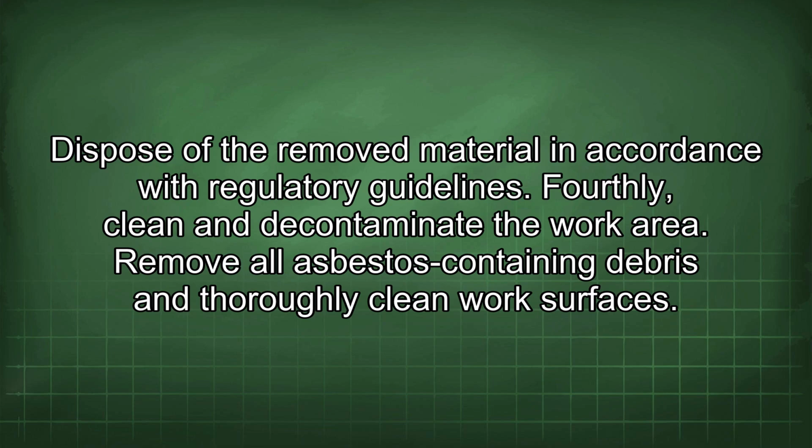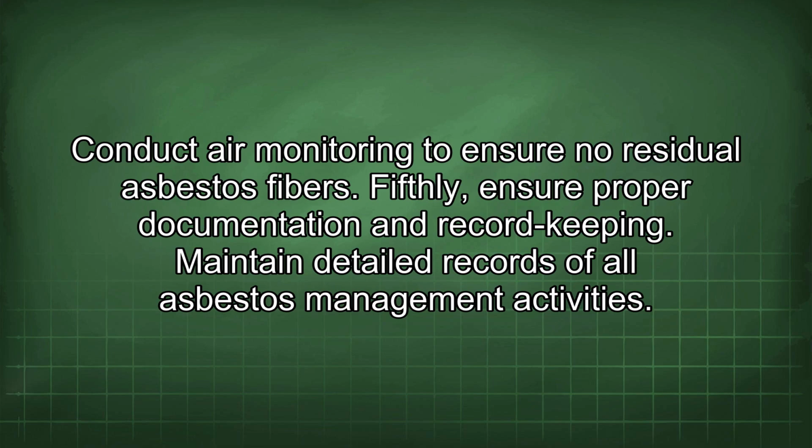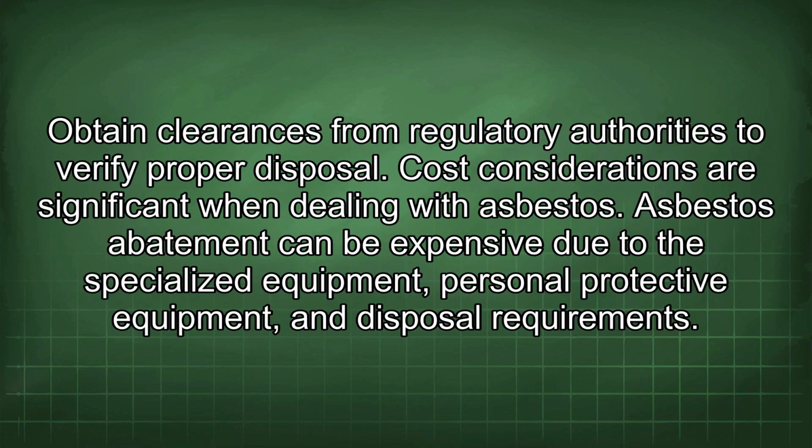Fourthly, clean and decontaminate the work area. Remove all asbestos-containing debris and thoroughly clean work surfaces. Conduct air monitoring to ensure no residual asbestos fibers. Fifthly, ensure proper documentation and record keeping. Maintain detailed records of all asbestos management activities. Obtain clearances from regulatory authorities to verify proper disposal.